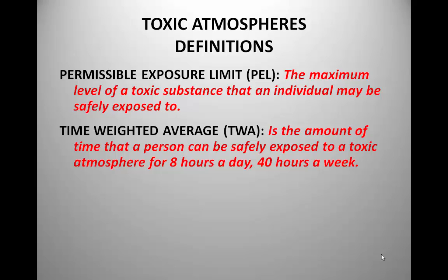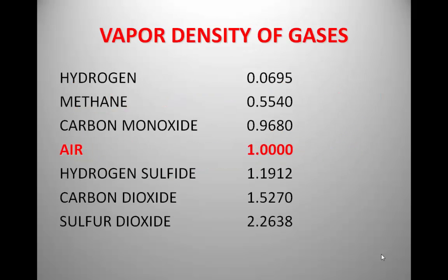And your vapor density of gases. Vapor density of gases is what gases weigh in comparison to air. This is pretty important for confined spaces because it's going to tell us where these gases are going to be in relationship to the location in the space.